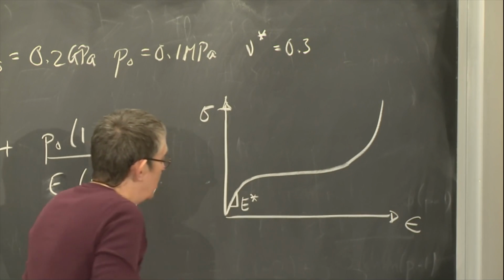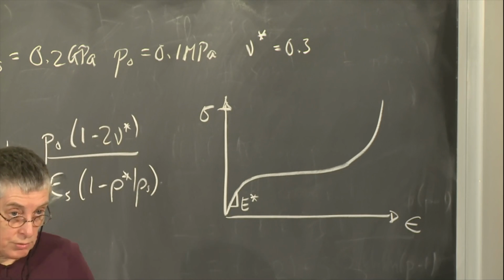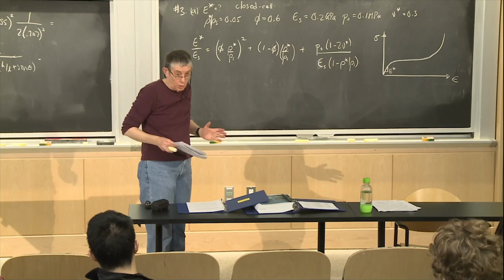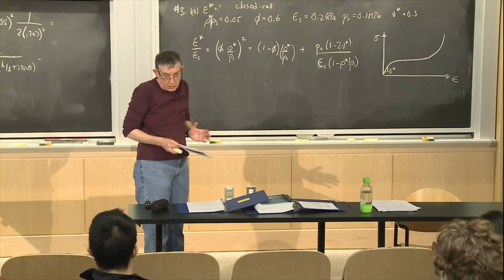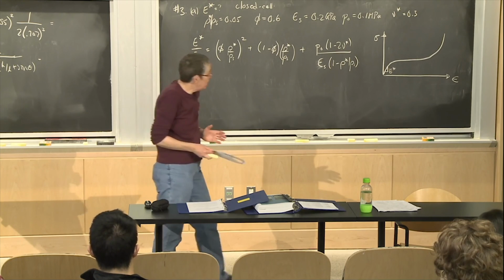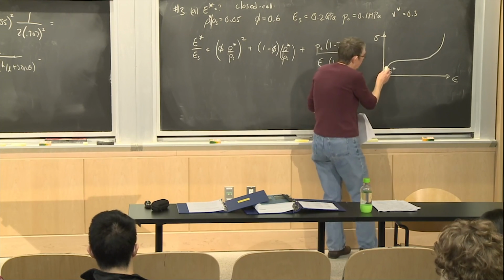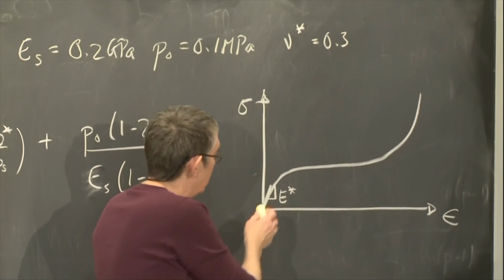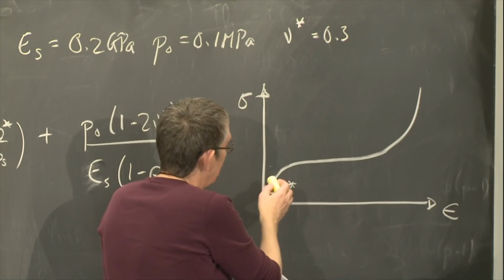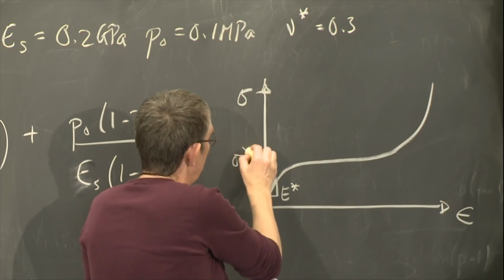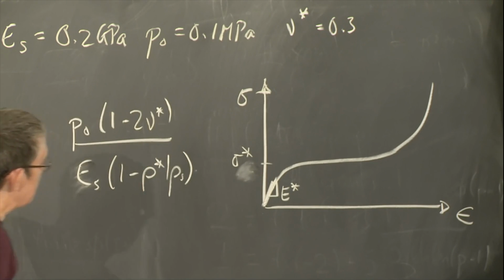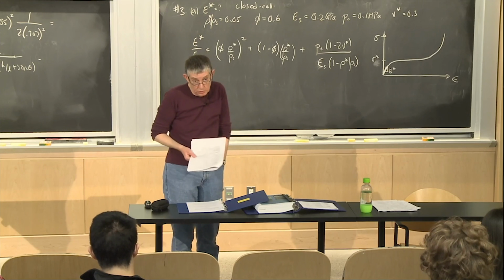The modulus is related to the initial stress strain relationship. And initially, they're not going to burst. You'd have to load it up to some amount of stress before the faces burst, right? So down at the beginning, the faces are not burst. And in some materials, when you get up around the plateau stress, or let's just call that sigma star, then they might burst, and then the pressure term would disappear and the face term would disappear.